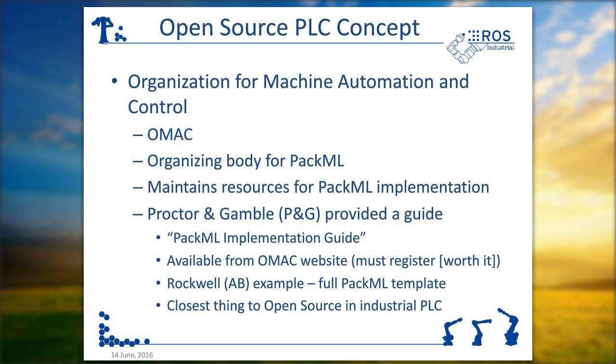So even though you may not have access to it, if you do or you have people that are interested, I highly, highly recommend this PackML standard as a way to make your PLCs much more logical and easier to maintain. And the interesting thing that I found is that for industrial PLCs, this is really close. The whole ISA 88 concept is really close to open source for PLCs. It's not like you can run Allen Bradley PLC code on a Siemens PLC, but you can pretty quickly translate the template and make it work. So it's really quite nice.